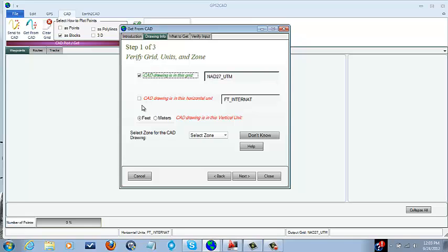However, grid datums are not that way. With grid datums, the world is broken down into smaller sections, or grid zones, and the X and Y are based off of some location within that grid zone. The specific layout depends on the grid you're using. For example, the UTM system will be different than the state plane coordinate system, or different from one of the common systems used in Europe. So the X and Y coordinate must be accompanied with the name of the grid and the zone it's referenced to.